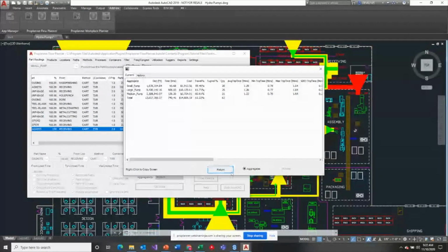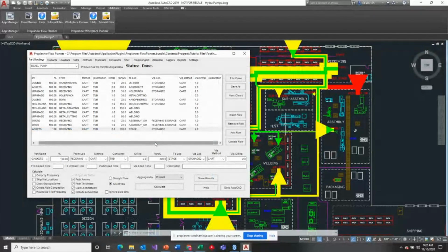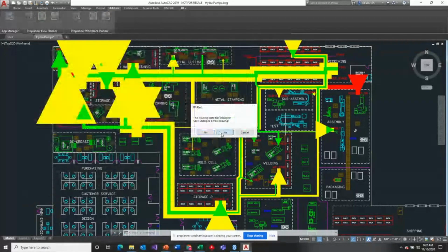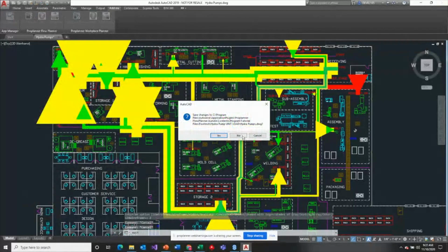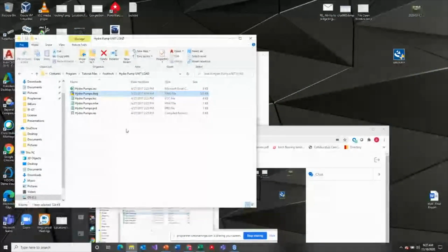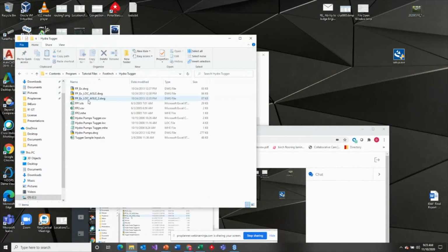So these are the very basics of a flow study. And what I wanted to do, to bring you up to speed with that, is let's now move from unit load studies, where we're moving fork trucks, and look at Tugger studies. Now to do that, I'm just going to leave this analysis here, and just to not create any confusion, I've got my tutorial file right over here. I'm going to go from the unit load tutorial in the foot-inch folder and go into the Tugger file, okay?